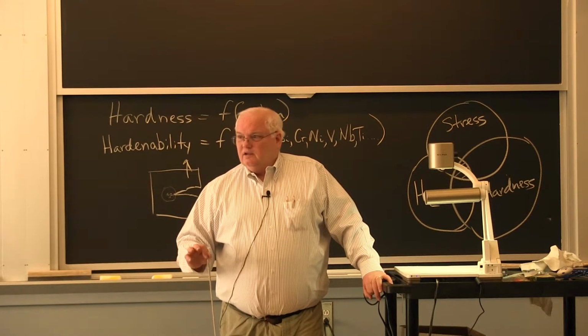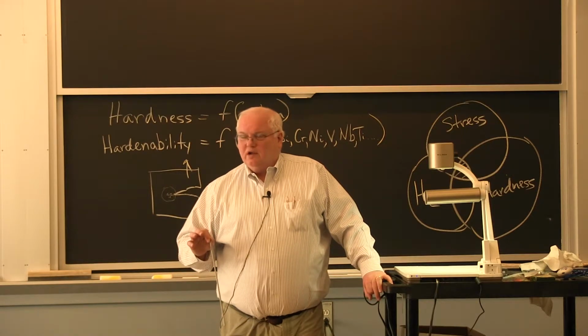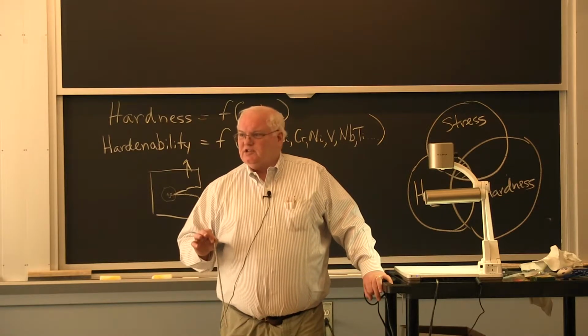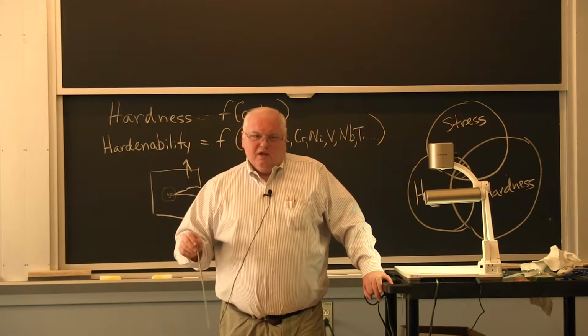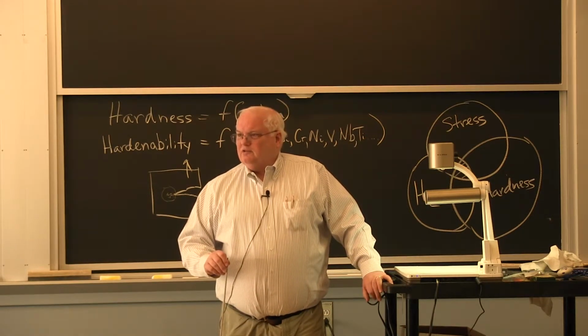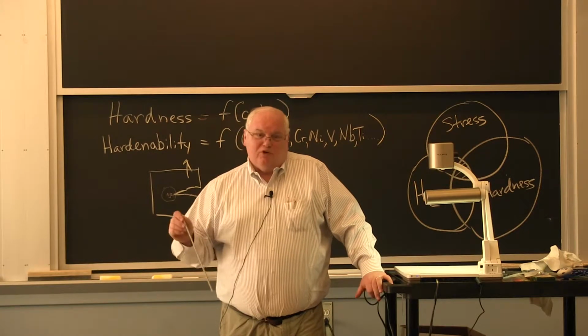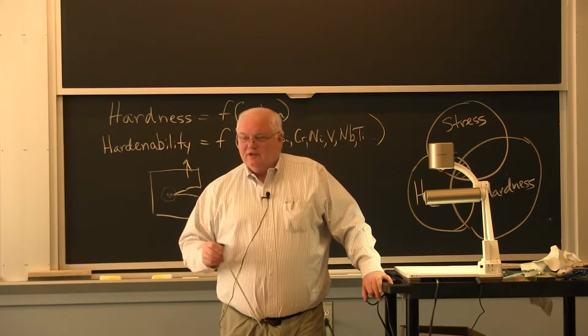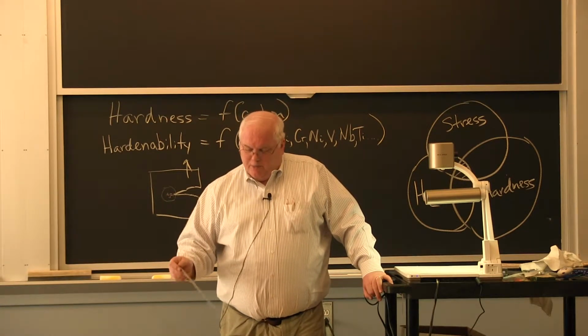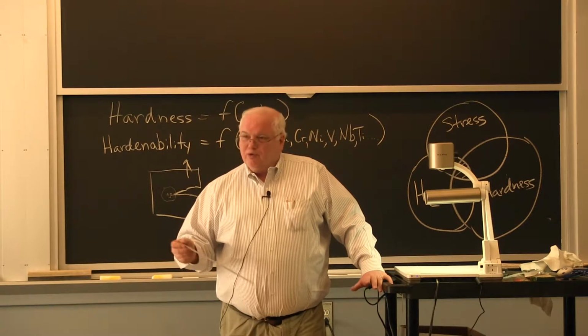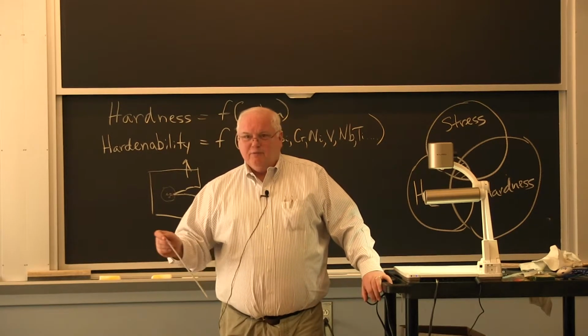Okay, the light intensity coming from the electric arc will give you a sunburned retina within 10-15 seconds. And if your sunburned retina is not very sunburned, all it does is for the next couple of days until the sunburn goes away, it feels like having sand in your eyeballs. You can't get rid of it. Okay, that's what I've been told. I've never actually had it. I tend to use safety glasses, goggles, or a welding helmet. But if you do it long enough, you'll burn your retina and you'll go blind. How about that? Even better, right?